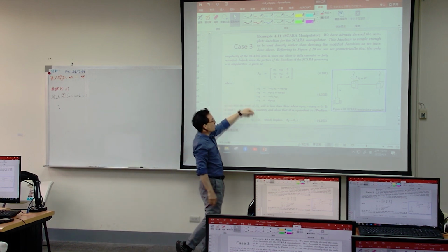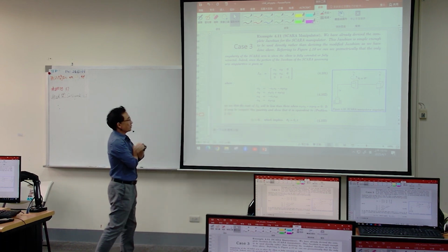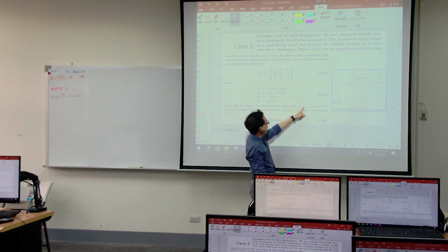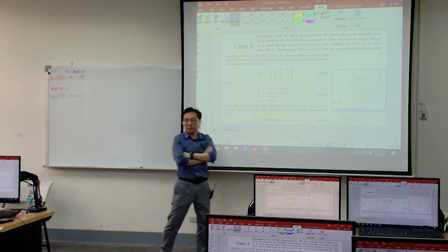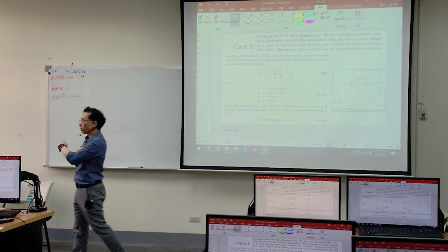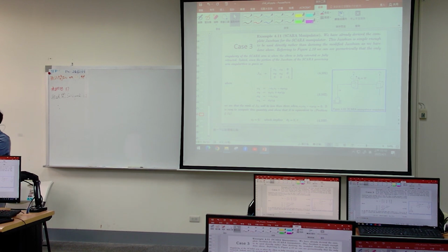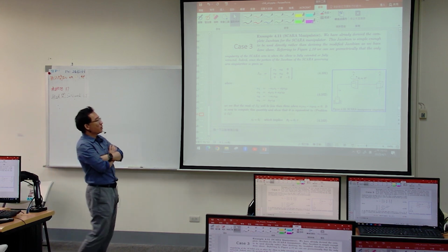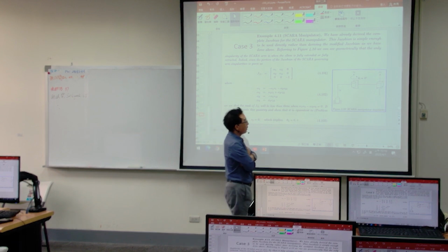So over here is correct. In this case, let's say the determinant equals 0, so you need to come out with alpha 1, alpha 4, alpha 2 equal to 0, then the singularity will show up. However, it comes out S2 equal to 0, sine theta 2 equal to 0. Then sine theta 2 equals 0 or pi, and the singularity shows up. So in this case, it shows from the geometry.